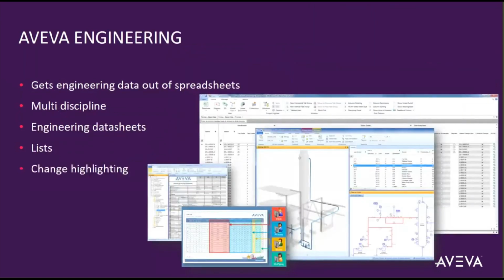AVEVA Engineering is basically where the process and mechanical people will work, entering their data, doing their calculations and things like that. From that, they'll be able to create the mechanical and process data sheets. I'll explain how the disciplines manage the data. But basically on an object, an example would be a pump, there would be attributes for process, attributes for mechanical, and attributes for electrical. The way the software works, it will control what discipline can change what attributes. So the process discipline can't change mechanical, and mechanical can't change process. So we've got full control over who can change what within the database.